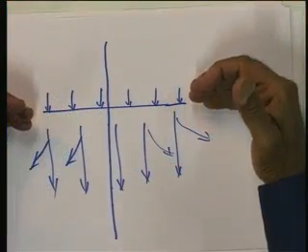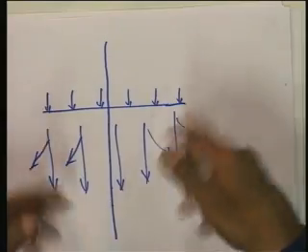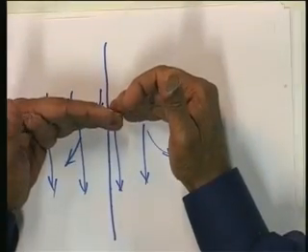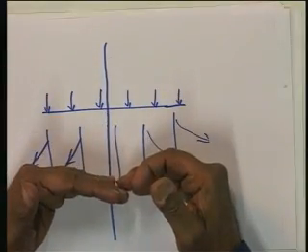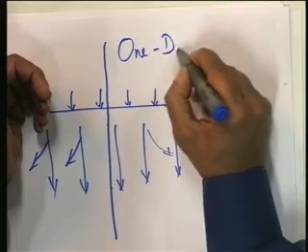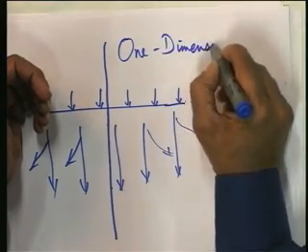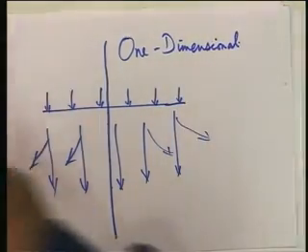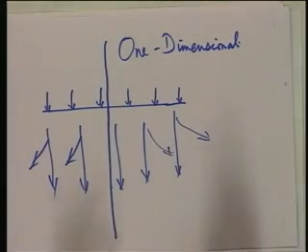What it means, as I said just now, is when a load is applied over a very large area, by and large, although the water may be moving out, oozing out in 3 dimensions, the compression of the soil is essentially in the direction of the load, that is in one direction, and this is what is known as one dimensional consolidation. And this is what we are going to initially see. We will later on see a special form of 3 dimensional consolidation, which is of very great practical importance.